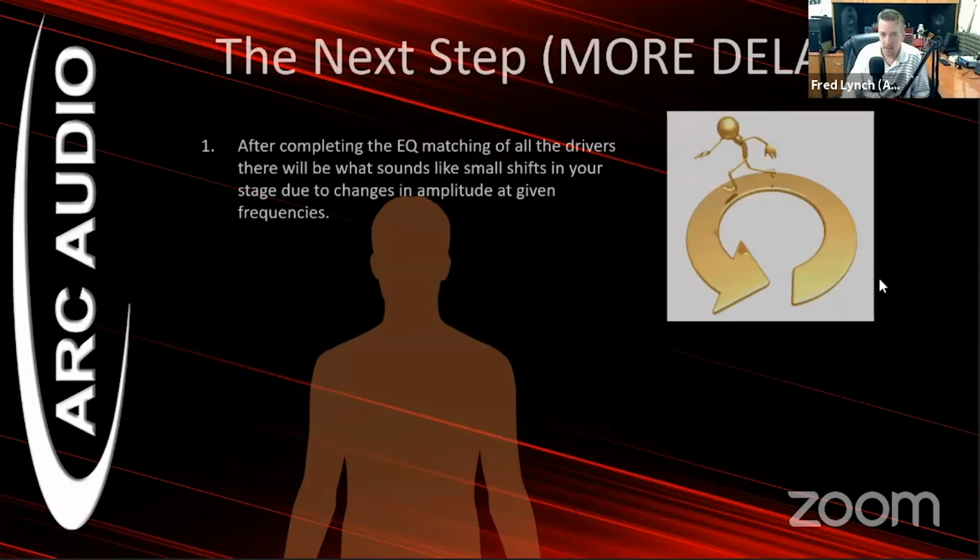Now, this is one that's kind of a killer for some people, is more delay. After you EQ the system and you have basically tonally matched and corrected left and right sides, you may notice that things are more defined tonally, but now you may hear some small issues in what you did with the delay. You can go back to listen to track 3, 4, and 5, the female track, the male track, and the real low male vocal track, and just do a re-verification. You might find that you're doing just tiny little tweaks, but you don't want to do any real major tweaks, because if you do major tweaks, you can affect your delay and your phase at a later time.